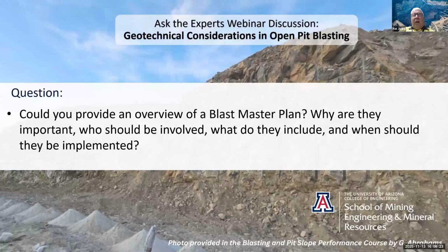We also need to talk about things like the bench reliability and the conformance. Are we achieving our targets? 80% reliability, 70% reliability, whatever it might be, depending on your design acceptance criteria. And the shovel performance. Are the shovels able to mine that muck properly? What's the fragmentation like, et cetera? And then this is also a good time to review our TARPs to address nonconformance.